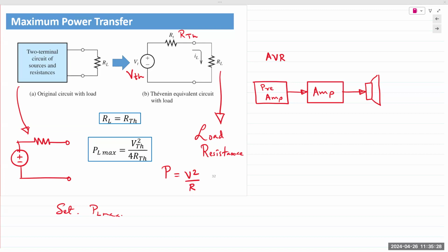Sometimes you may think that the resistor is in series, but it may not be in series. You have to keep in mind, a series connection requires only 1 junction and no more than 2 connections at that junction. So if that condition is met, then you can cut out that voltage source and that resistor.